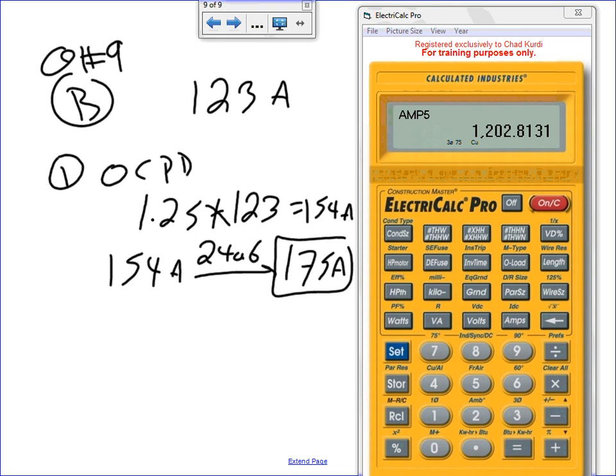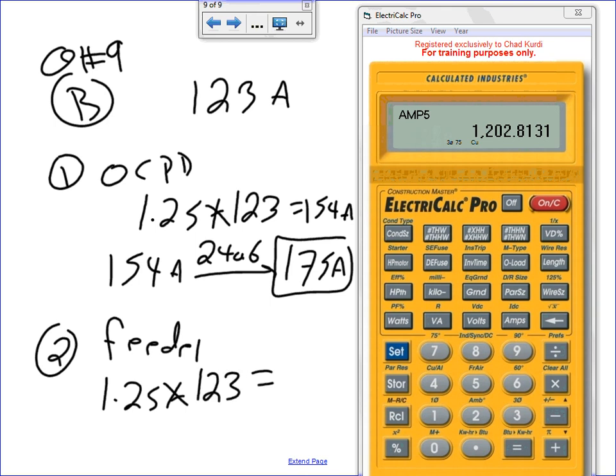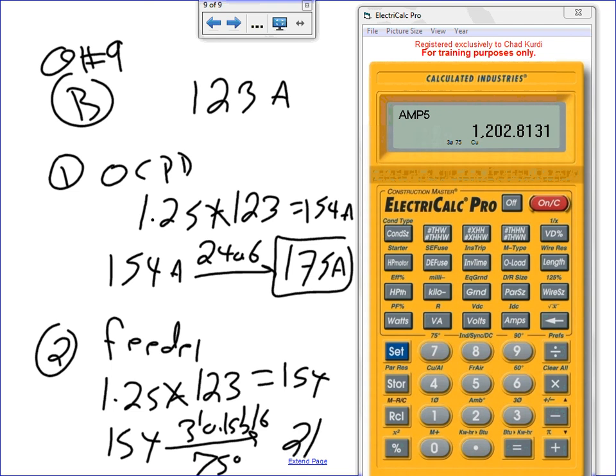Okay, so you take the feeder, continuous load, remember. Now the feeder size, piece of cake, Chad, the same calculation, 1.25 times 123 equals 154. Take the 154 all the way to 310.15(B)(16) under the 75-degree column, and guess what you get? You get your two beautiful 2-aught. How many conductors? 4 conductors for a 3-phase, 3 conductors for a single phase. Okay, doing the same thing on A.